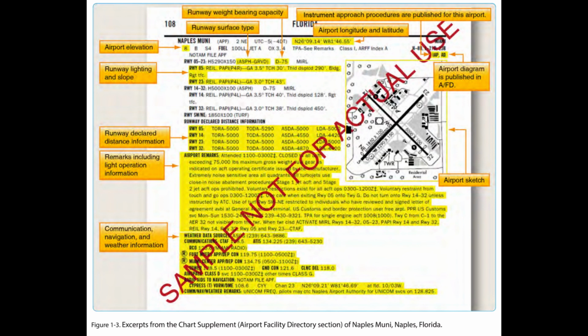1. Clearance bar lights. 3 yellow in-pavement clearance bar lights used to denote holding positions for aircraft and vehicles. When used for hold points, they are co-located with geographic position markings. Both flight and ground crews, Part 121 and 135 operators, are required to comply with SMGCS plans when implemented at